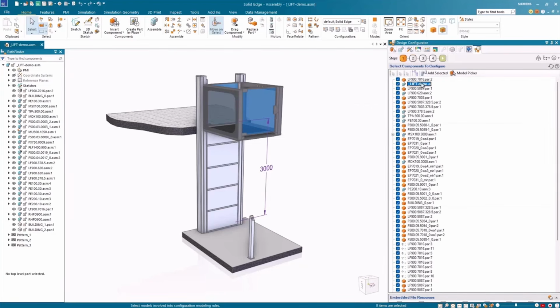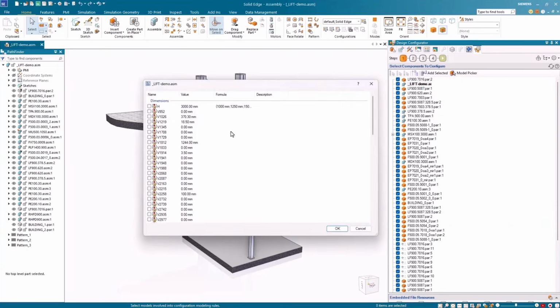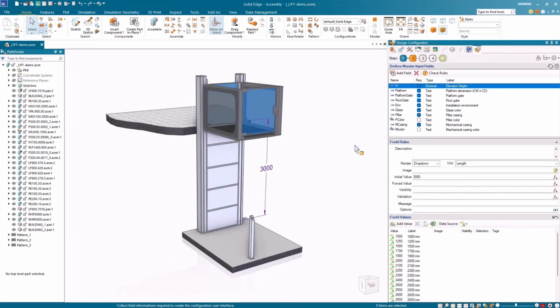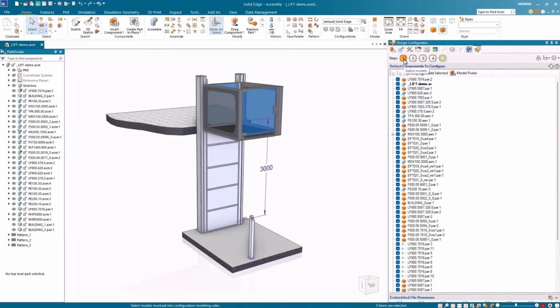One thing we added about 2 years ago on the Design Configurator was the quick model actions. So if you're not sure what to do, you can use these to not only add the needed input, but to also add the needed model actions. And they can work for multiple different things within the Solid Edge Design Configurator. For example, we just did a quick action for one of the variables within the model. And this not only created the variable for us automatically, it also created the values and the model action. And again, so much customization. We can customize the name and so on.